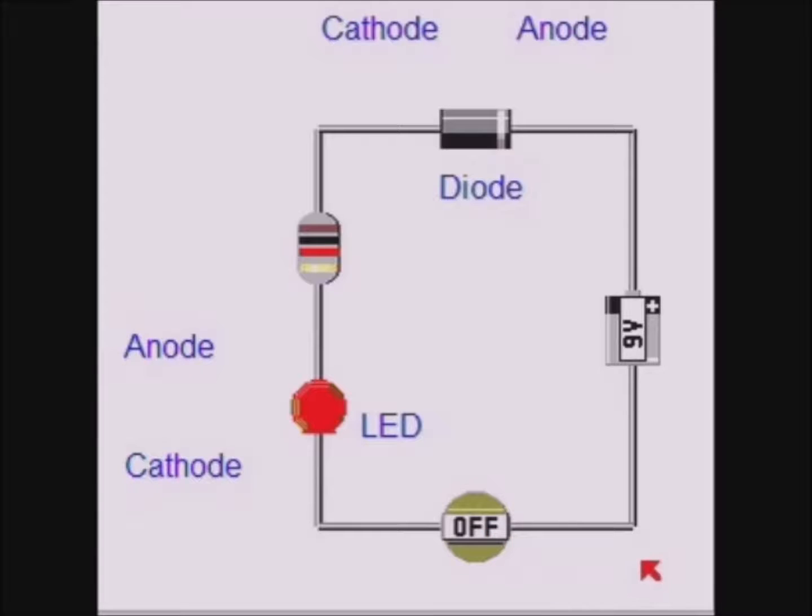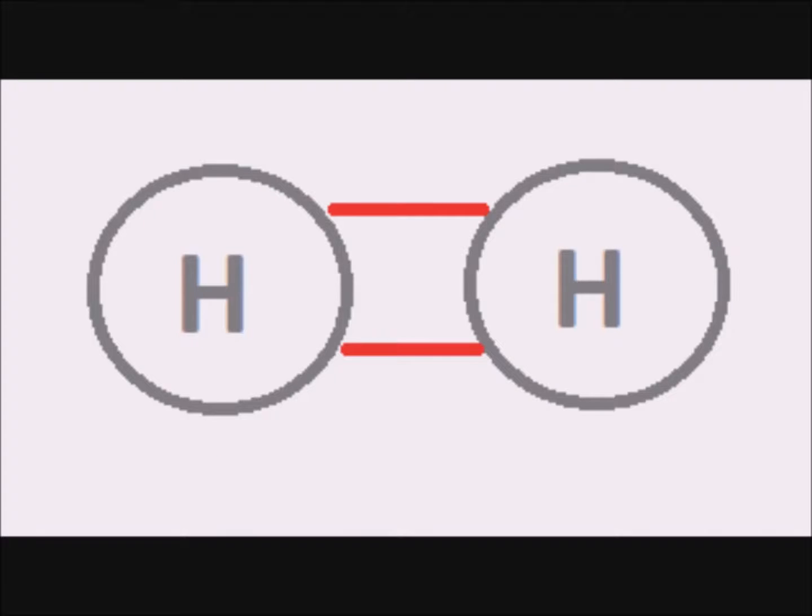This is the valuable feature of a diode. It allows current to flow in one direction only. One use of a diode is to protect a circuit in case the battery is connected the wrong way around. Initially the diode was developed for rectification of radio signals. More about that later.